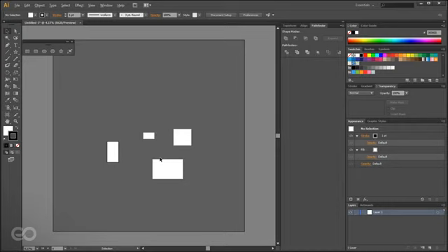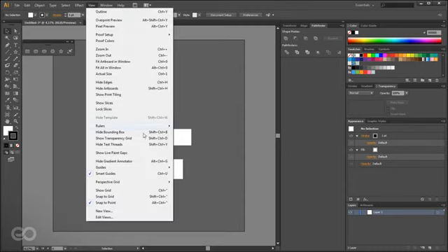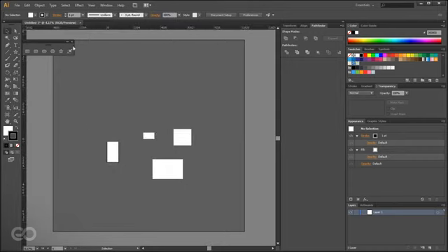So now this creates a particular problem for most people because it messes up their rulers, or it doesn't actually work with the rulers. So let me just show you exactly how to work with them. Now if I go ahead and turn on my rulers, which is basically going to View and Rulers, Control R, to get my rulers. Here you can see that it has some kind of a setup, and you can see that the 0 value and the 0 value here are at this corner of this page. If I go click on another page, you can see this value shift.